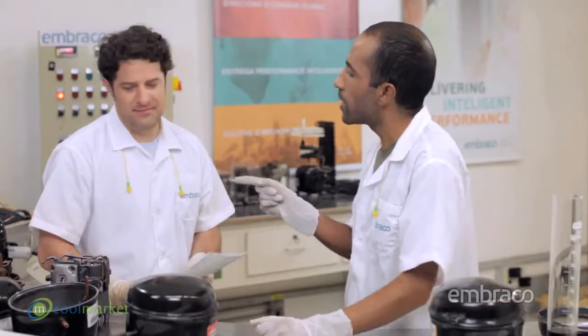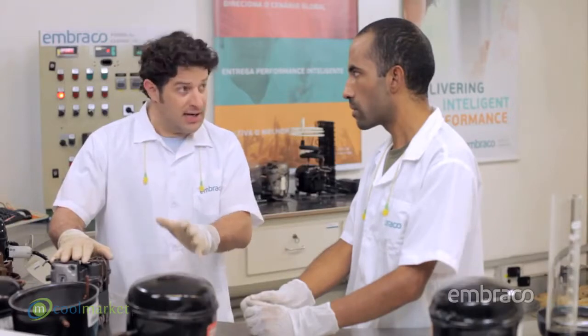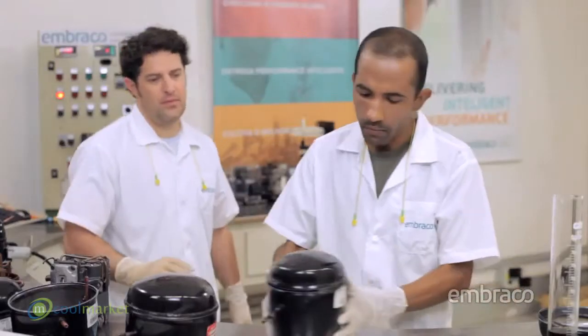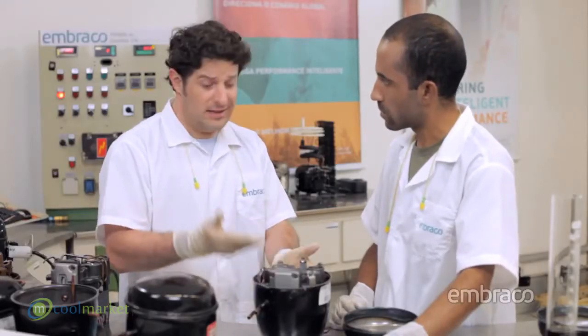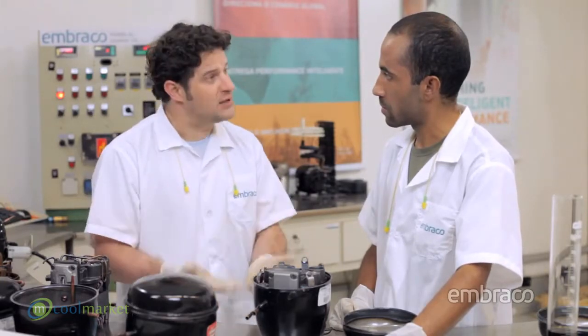Yes! Taking advantage of this opportunity, Peter, if the compressor suffers some impact, but doesn't show any apparent damage, does it still work? Mark, although the housing is made of steel, the compressor should be treated with care, since the impact can cause severe damage to internal components, even if the housing isn't dented. But doesn't the compressor have springs to absorb impacts? Internally, the compressor has shock absorption springs and is tested to withstand normal shocks during shipment of the compressor or refrigerator. Now, excessive impact may damage the compressor's radial clearances, causing it to not work properly.